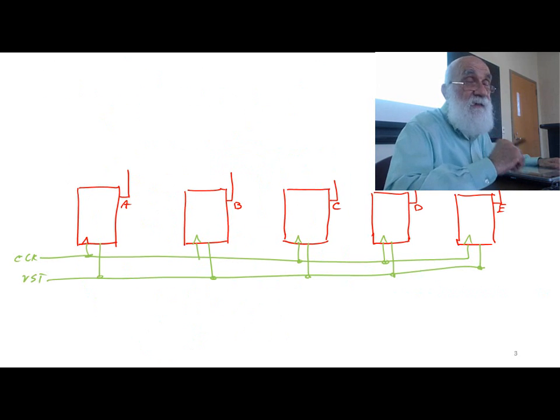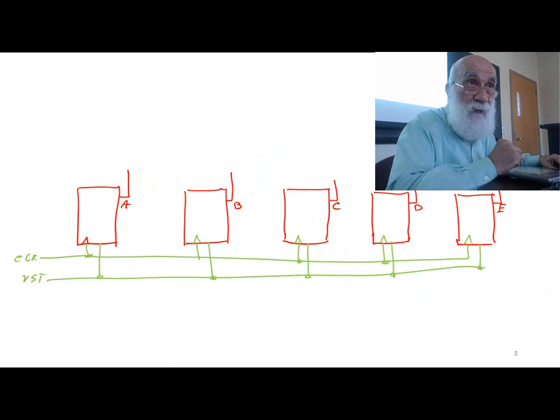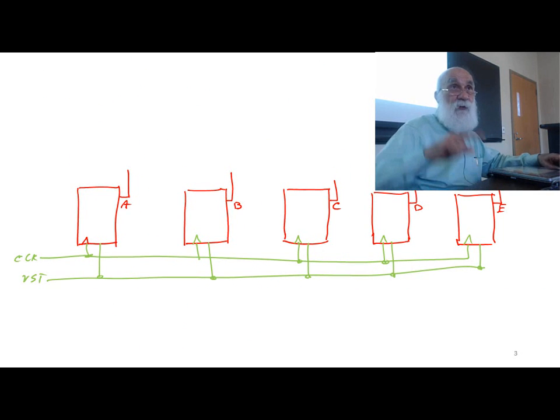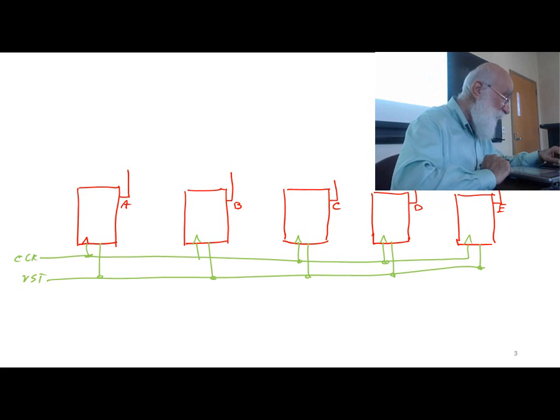Now, if I had done the binary mapping, meaning that I had 3 flip-flops, I could make the output of the flip-flops the same as the state variable, so I wouldn't need any logic for the output. In this case, though, this is not the situation, and therefore I do need some extra logic for my outputs, which we will be seeing in a few minutes.